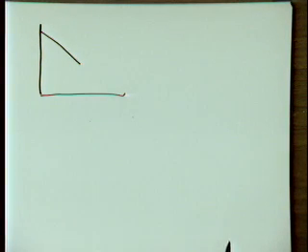Yes? For the top, do you just assume that since the input is VDD, the top is just off, so it's just like an open circuit? Yes. Okay. Yes, because remember, we have a step function. The PMOS goes off instantaneously. Unless, obviously, there would be some leakage going on.